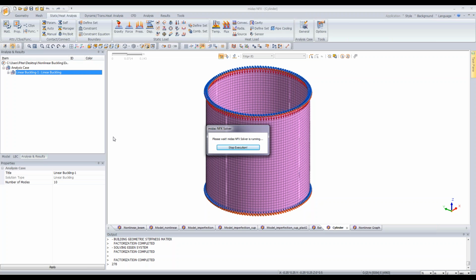And this linear buckling analysis, excuse me, is commonly used to add the imperfections with the modes that we are expecting. So all the time it's very important to perform a buckling sensitivity study and to figure out which type of mode is important for your nonlinear study. At the moment I will show you how to add this imperfection from the result of the eigenvalue analysis, but at the same time, using this technique, you can provide imperfections defined by yourself.